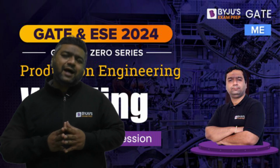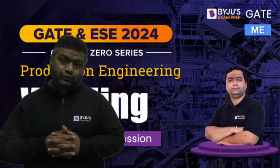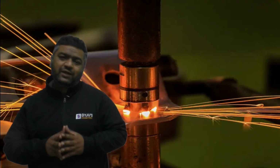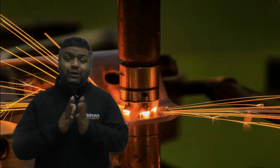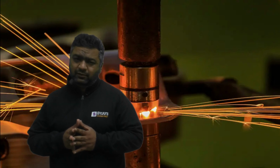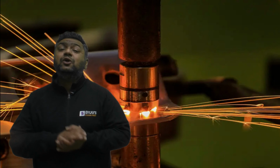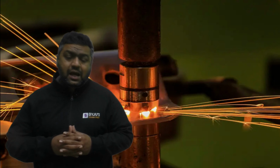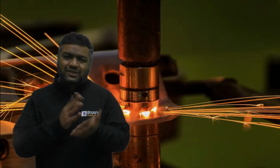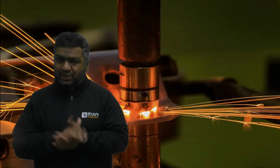As we have already seen the arc welding, which was a high voltage and low current welding process. Today's process, which is resistance welding, is just opposite of that. It is low voltage and high current welding. When I am saying high current welding, the current ranges are going to be always more than 10 to 15,000 amperes. And my dear, here we will not only be using the heat as well as pressure. So it is going to use the application of both heat and pressure.